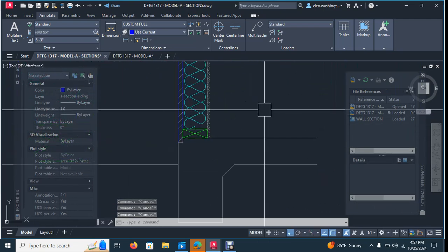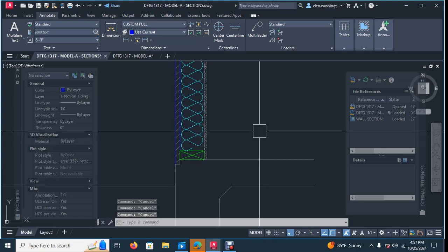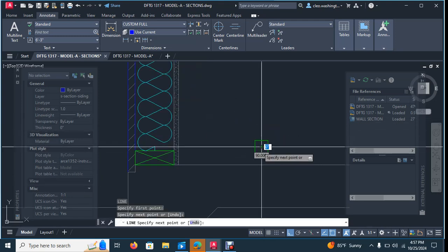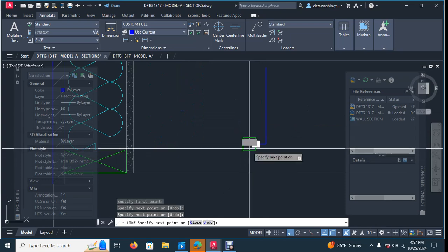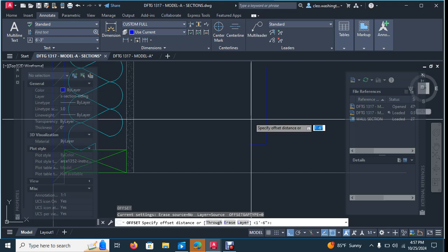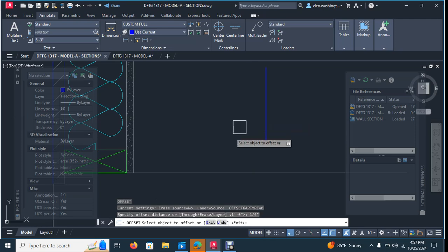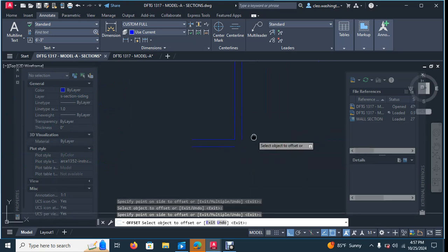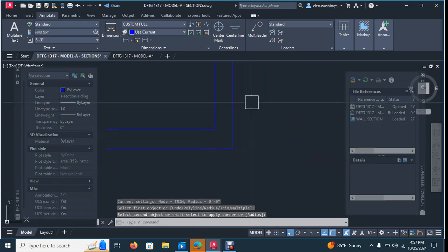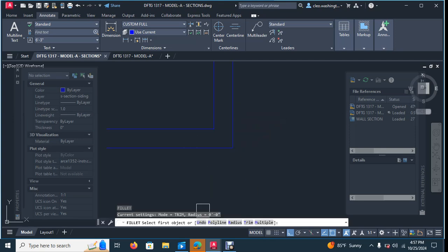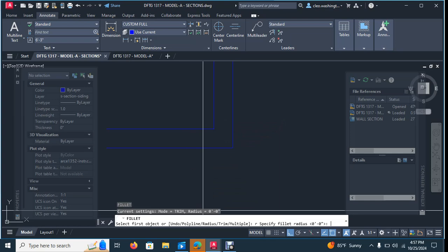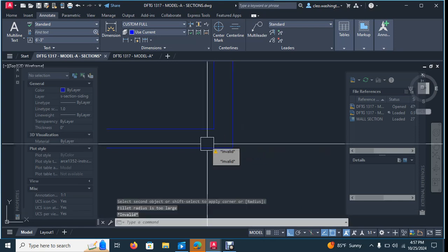And let's draw an anchor bolt. So what you want to do is, I'm going to draw a line. Okay. And you can just do like that, and then just offset. And you want to offset that, let's just say a 1/2 inch. Well, let's say 1/4 inch. Yeah, like that. I'm going to fillet it. Now hit fillet again and type R for radius. And then tell it you want to give it a radius of 2 inches. Hit the space bar, come back, select this line and then that line.